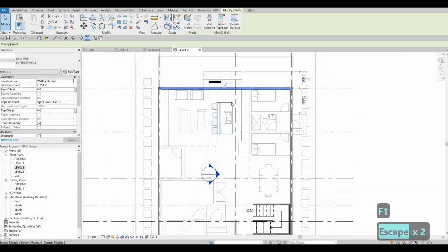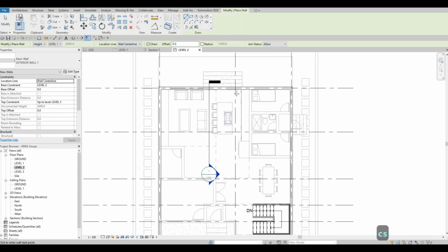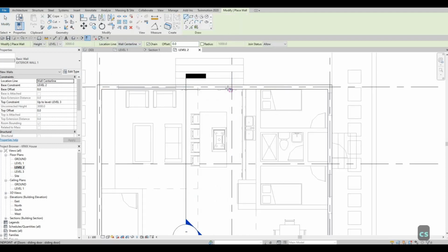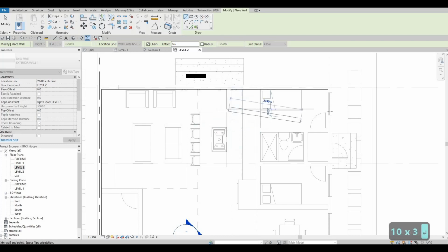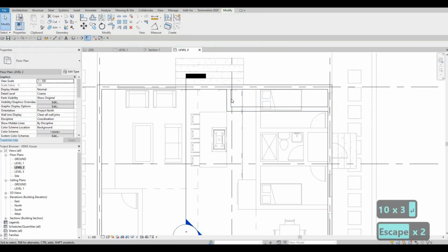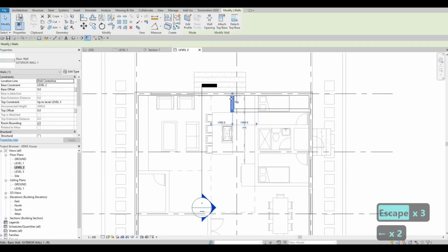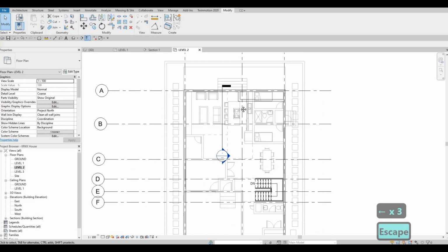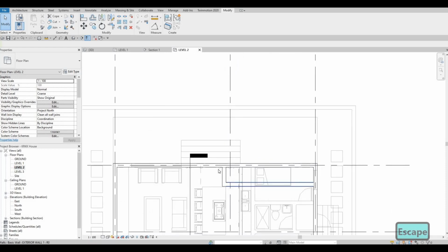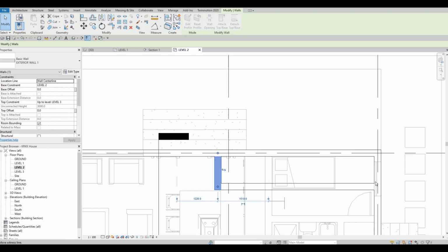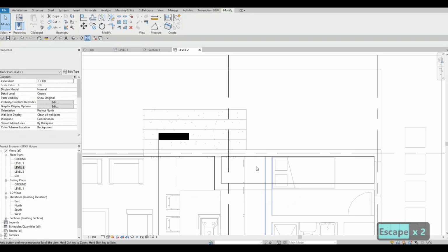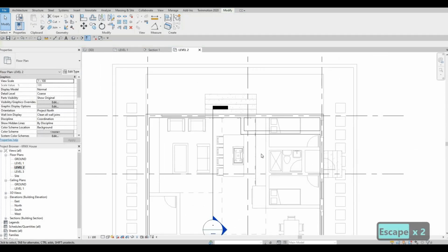So I'm going to select the exterior wall again, CS, and then from here I'm going to add roughly around 1000, and then pulling it like that. I'm just gonna go over a little bit onto this number 2 grid. So in total, I'm going to have it at 4760. And then we could TR, trim and extend.